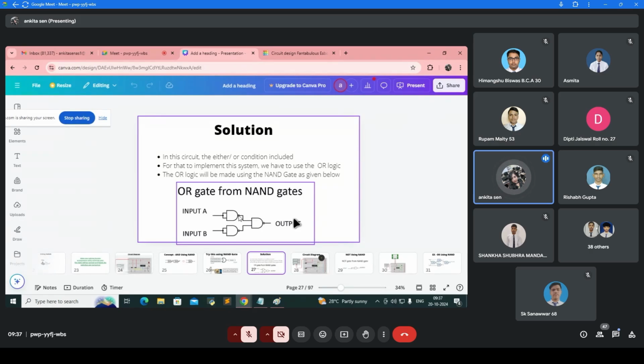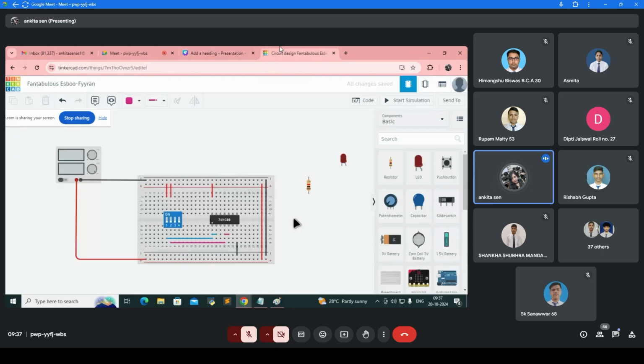So next, what we have to do? This NAND gate output needs to be connected to another NAND gate input. The same thing will be happening for the second one also. This is output 1, this is output 2. So we need to get another set of NAND gates. We can use 4A 4B, or we can use 3A 3B, as per your choice. This is the 4A, this is the output that can also be taken, or you can choose this set of inputs also.